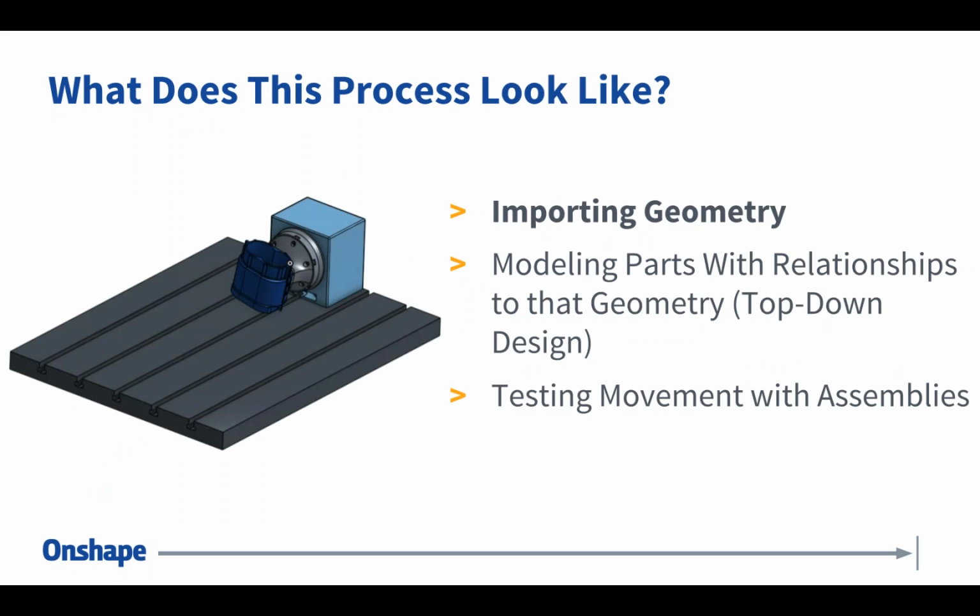The process is really the same regardless of what CAD application you're using. Oftentimes, you're given a file, whether that file is coming from the engineering department or from another company and you're doing the design or the manufacturing work for it, oftentimes it involves importing geometry. And of course, that means importing STEP, IGES, Parasolid, SolidWorks, whatever the format may be.